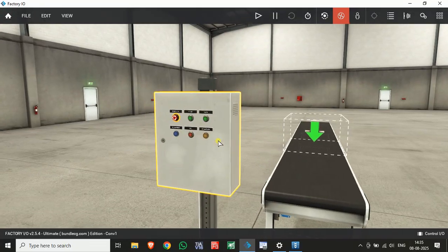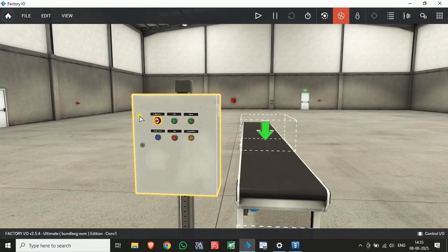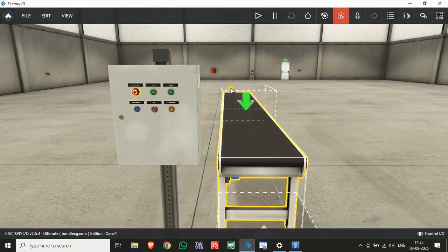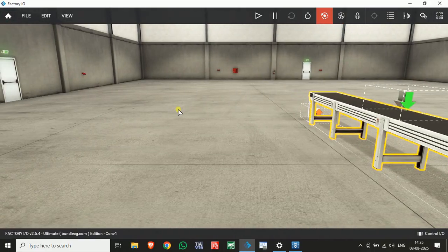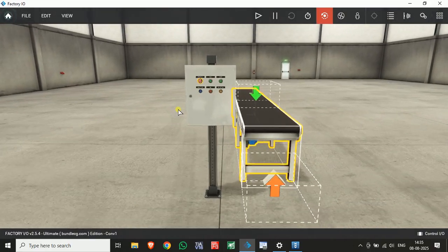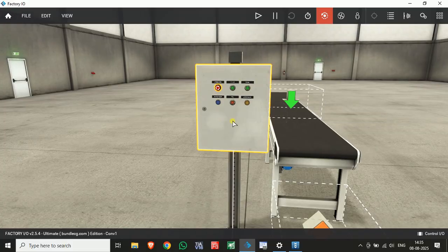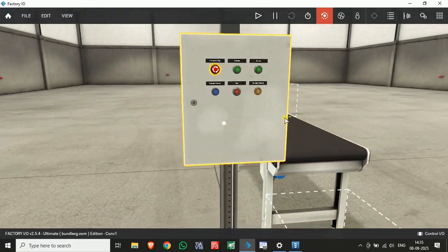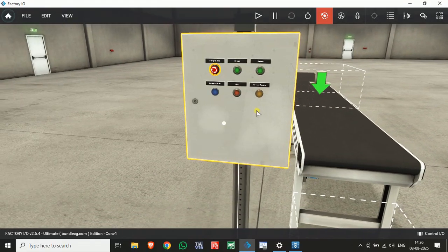Okay, it is easy to move in this orbit camera. To rotate your perspective, click on the point of focus, like here I am using a conveyor edge. Once I click that, that's my point of rotation. To understand better, you will work with the orbit camera. Orbit camera is very easy to work with, using navigation keys to move left, right, front, back, and using double click at a point of an object to pan and rotate.